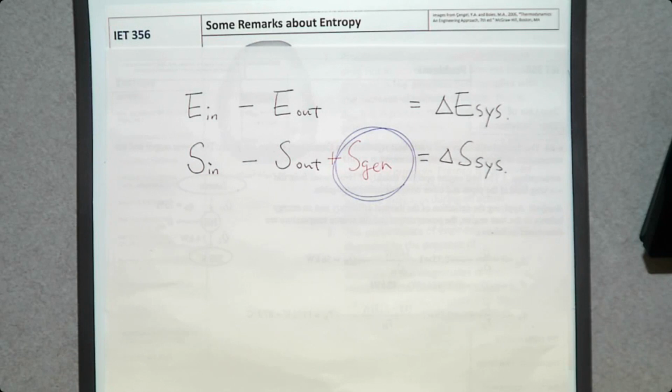Then how are you going to choose what is the best design? What is the plan that you want to pursue? You can calculate entropy generation for plan number 1, plan number 2, plan number 3, etc. And the one that has the least entropy generation is the most efficient way, so you can pick that one.